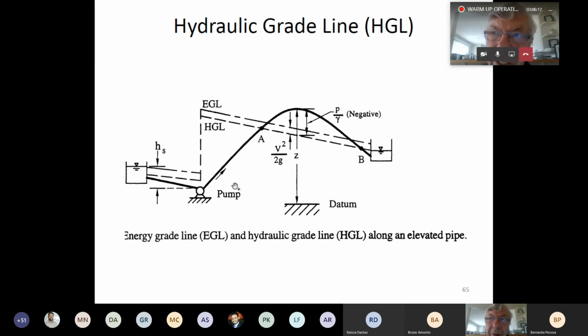And we've got to be careful with some of the products that we ship because there are high vapor pressure liquids. Those are fluids that at 38 degrees C have a vapor pressure of about 1.4 megapascal. So they would be liquefied petroleum gases, ethane, and the very light hydrocarbons. And you've got to be very careful with those because you can get two-phase flow. In other words, if the pressure drops, you'll get a gaseous phase and you'll also get liquids. And the separation of gas and liquids is dangerous.